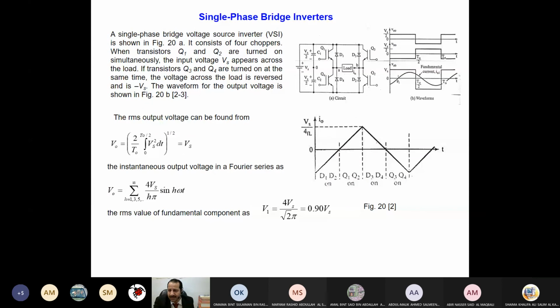And also the same discussion for using a freewheeling diode. We discussed this circuit, but for one leg. Here, the freewheeling diode will provide another path. As you can see here, this increase will be handled by two switches, one from leg A and one from leg B, and here it will be handled by 2 diodes, and then again by 2 switches, 2 diodes, and so on. The same formula derived before applies, I don't need to go through them.